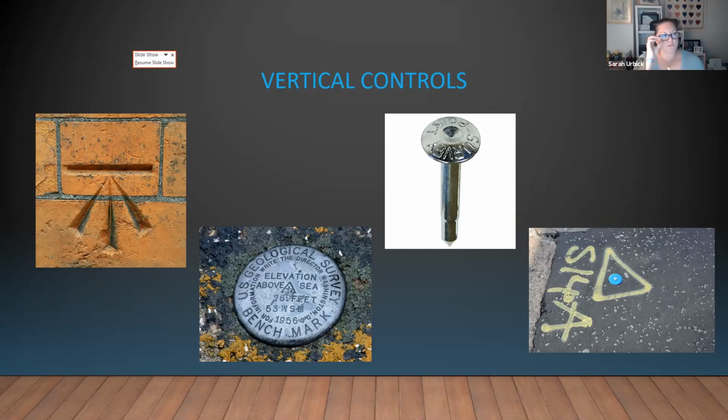Okay. This little nail is actually a temporary survey marker. So we might start with a USGS benchmark, and the surveyor will go out and, based on that information, locate a point within our site where we would be working, where we want to design our project, and we would put a temporary mark there.